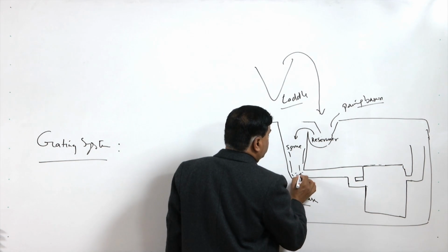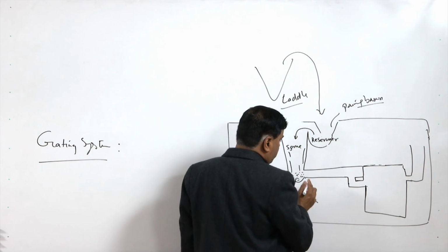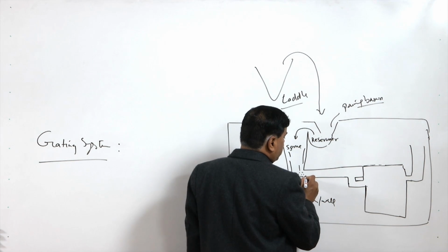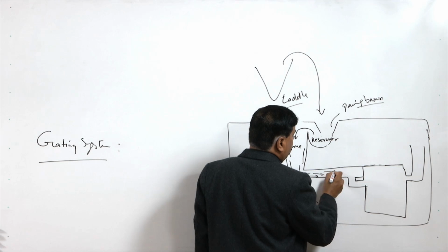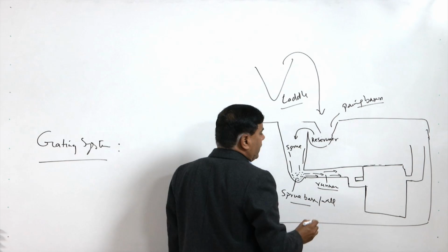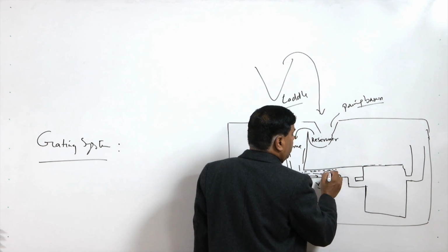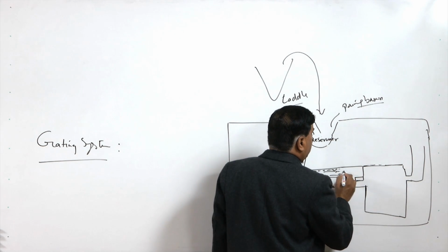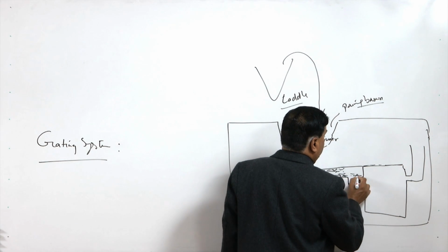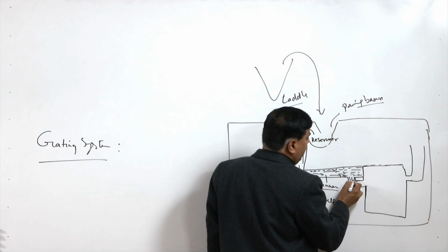So, this is another reservoir which is created. The molten metal reaches the sprue base or sprue well, and then there will be a change in direction for the flow of the molten metal into the runner. So, this is basically a runner. When the metal is flowing into the runner, all the lighter impurities will be floating over the top surface. Sometimes a runner extension is also made, so that molten metal flows directly into the extension, and the clean molten metal enters through this ingate.